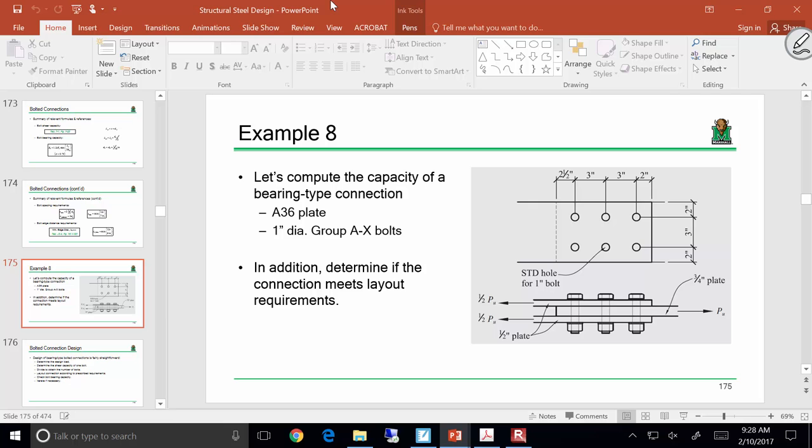If we look at the plates transferring load to the right, we've got 3/4 inch of steel. But the plates transferring load to the left, we have 1 inch, because we've got a 1/2 inch here and a 1/2 inch here. So we have a greater thickness of steel transmitting load in this direction. That makes sense? If that was the only variable, maybe I could say we just need to check this one, and that's fine, because less steel, this is going to be the weaker plate. This is going to be the one that governs.